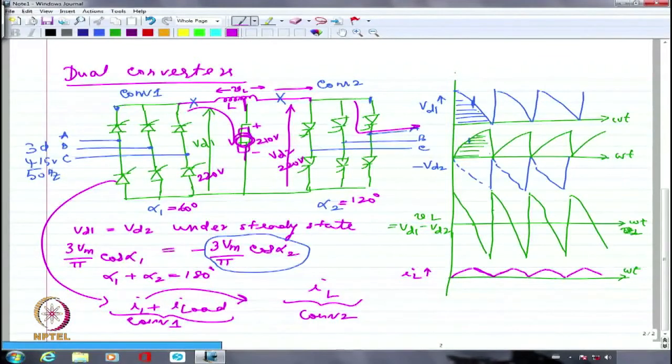Fine. If I want to bring down the speed of this particular DC motor drive by doing braking, previously what I should have done is to reverse the direction of the armature, make alpha, which was originally 60, go to the other side. It's a big task because suddenly I had to jump from some alpha less than 90 to some alpha greater than 90.